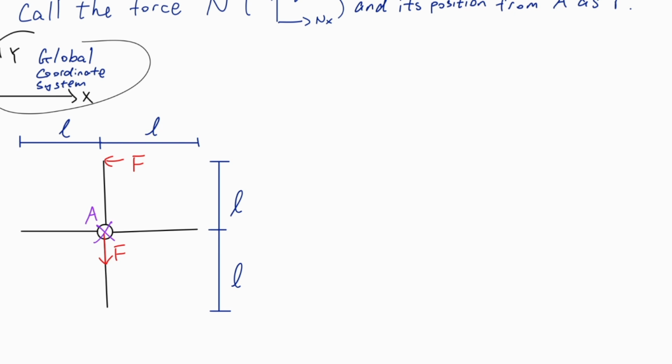Firstly, we'll do the forces sum, okay? The magnitude and direction have to be determined by the force sum, and the position is determined by a moment, right? Because there's only one magnitude and direction that can cancel out the forces. We have to do that first. Sum of forces horizontal is 0. Once again, we're going to take rightwards as positive. I suggest, honestly, just find a direction you're comfortable with and stick with it.